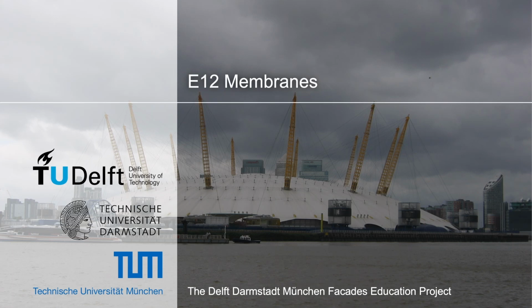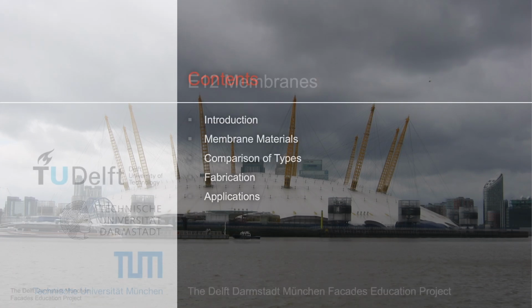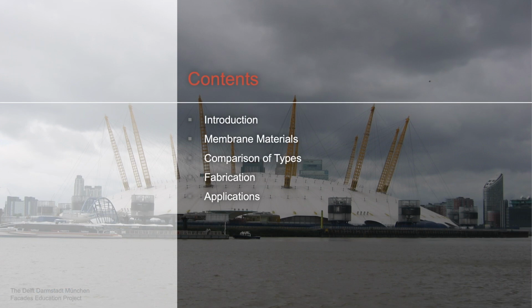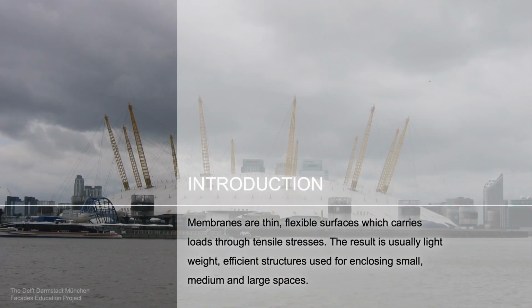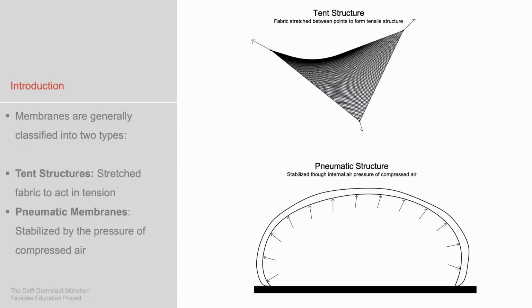Lecture 12, Membranes. Setup, as usual: introduction, membrane material, comparison of types, fabrication and application. Membranes are thin, flexible structures which carry loads through tensile stress. The results are usually lightweight, efficient structures for enclosing small, medium, and large, mainly large spaces. It's a light structure, so large spaces.